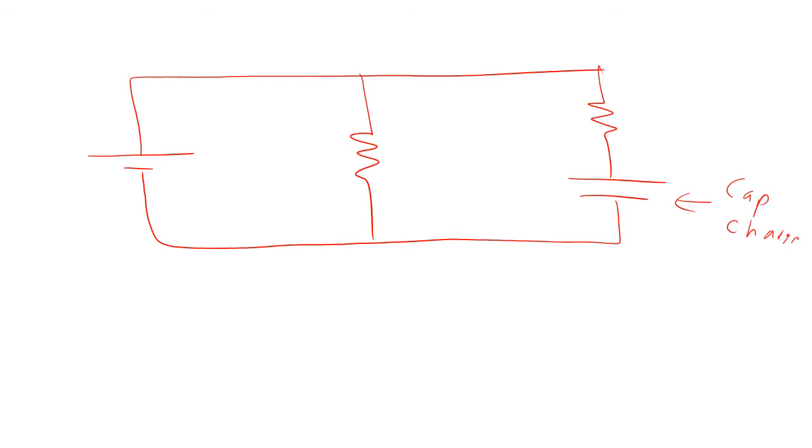How long is that? Well, it depends on the time constant. Normally you'd say if you wait like 10 time constants, there's virtually nothing much left to change. Often you just say 4 or 5 time constants is pretty well charged. But if you wait 10 time constants, there's almost nothing left to change, and so that'd be a long time. It just depends on how long the time constant is.